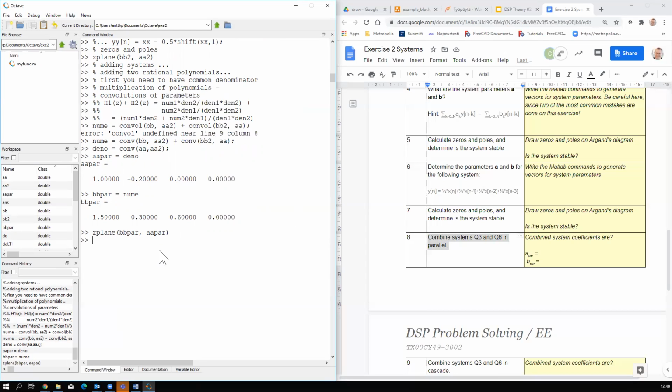For non-feedback systems, it's easier to combine, since then you automatically have the same denominator polynomial, which is simply scalar 1. So you then need to just add these numerator coefficients together. But since we had a feedback term, it immediately changes this one. A little bit cumbersome operation, but on the other hand, it's not that bad.